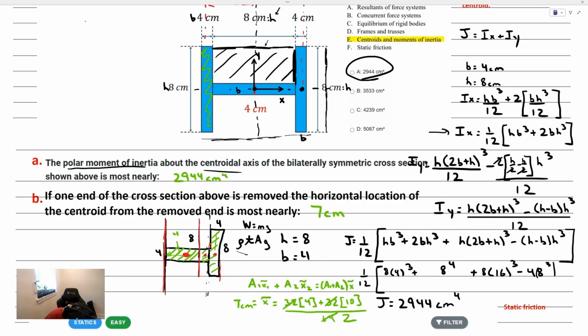This entire term represents a weight, and we multiply that weight by a centroidal distance. So let's say we replaced each of the area terms by density, thickness, area, gravity. Each of these terms, the density, the thickness, and gravity are all common. So we end up crossing them out left and right side, and we end up producing moments of areas.